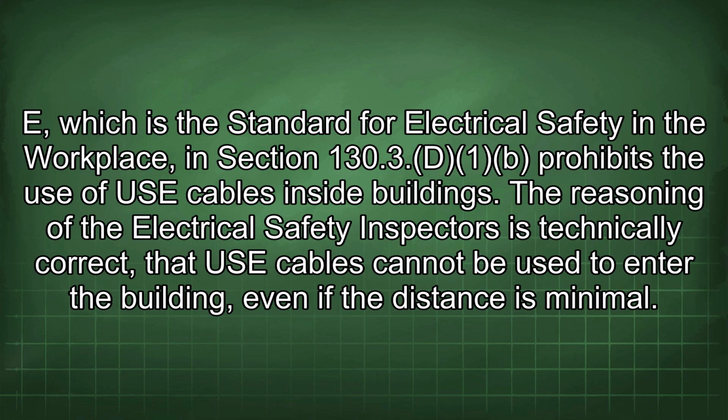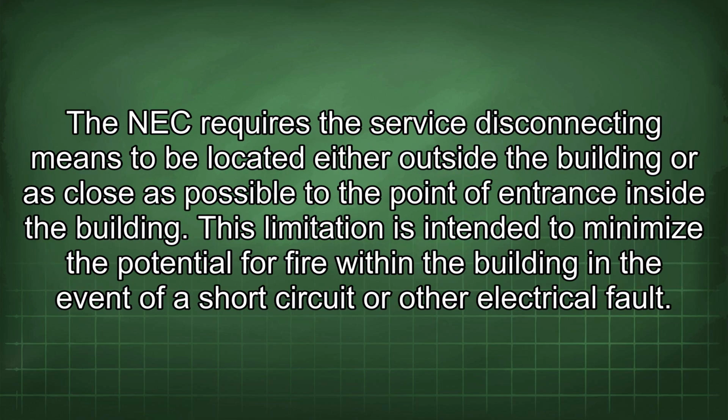The reasoning of the electrical safety inspectors is technically correct, that USE cables cannot be used to enter the building even if the distance is minimal. The NEC requires the service disconnecting means to be located either outside the building or as close as possible to the point of entrance inside the building. This limitation is intended to minimize the potential for fire within the building in the event of a short circuit